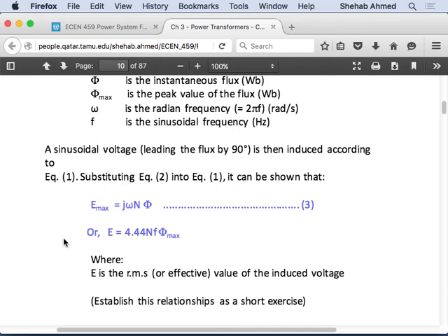So what people are doing now is adding power electronics. You have 50 hertz coming in, you want 50 hertz coming out, but you don't want a huge transformer. We saw how big these transformers are, so you want to live with a smaller transformer. What people are proposing as the future solid state solution to power distribution is: you bring in your 50 or 60 hertz, you use power electronics to convert that to high frequency, put a high frequency transformer in there, and then use power electronics again to bring this AC high frequency back to 50 hertz.